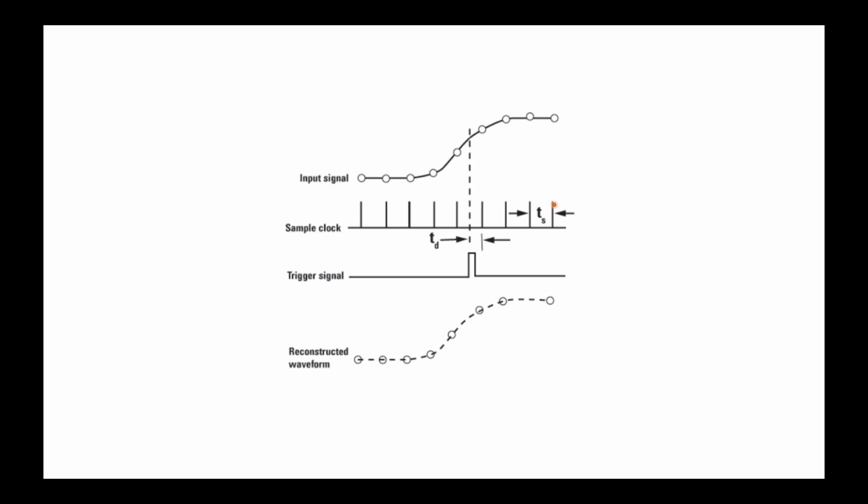But well, I shouldn't say impossible, because nowadays you have 80, 90, 100 gigasample per second A to D converters, and that's going to continue to improve. But those are the highest cost solutions you can find in order to digitize a signal with A to D converters that have hundreds of gigasample per second sampling rate. So a much simpler solution can be found if you give up on having a real-time sampling and perform subsampling. And that's how this instrument works.